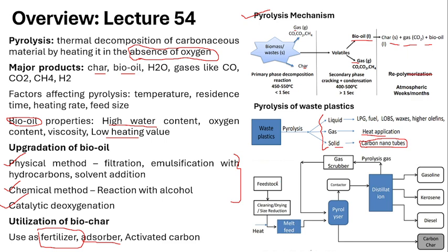Okay. Now, this is the process flow of waste plastic recycling. If you see, the feedstock is cleaned, dried, and size reduced. So we know that we have to remove the bulk particles and make it homogeneous and uniform in size, and then heat is provided so that the melt feed is here. It is sent to the pyrolyzer, where, because of the pyrolysis process, the decomposition of the carbonaceous matter occurs, and then it is distilled.